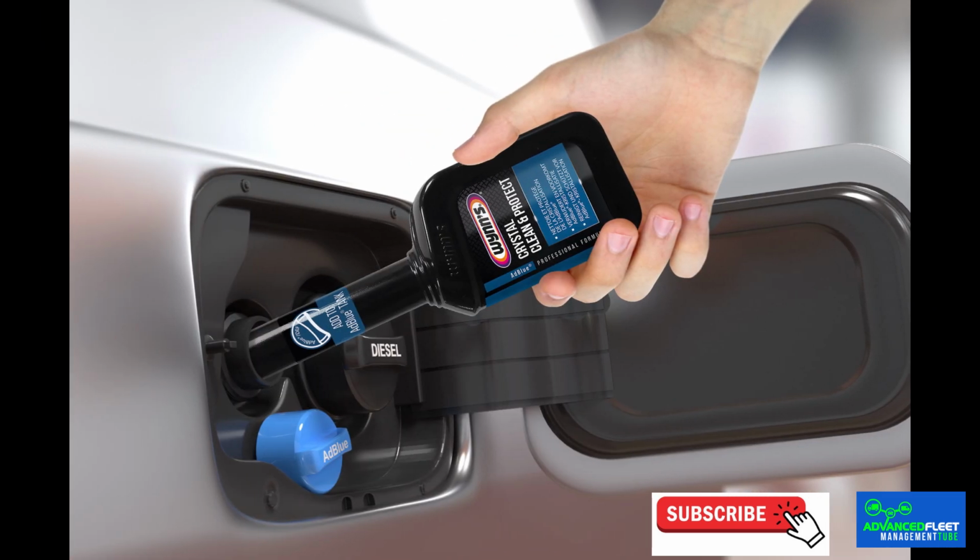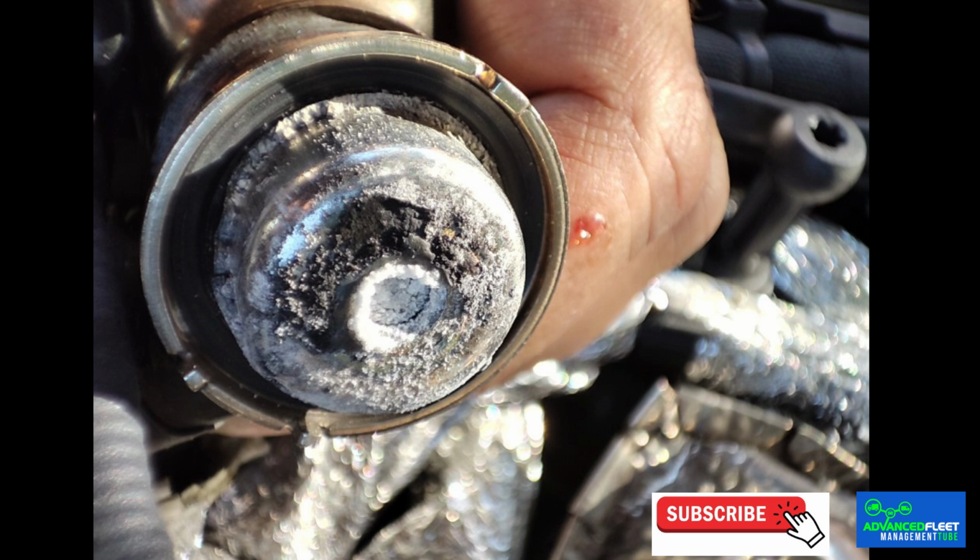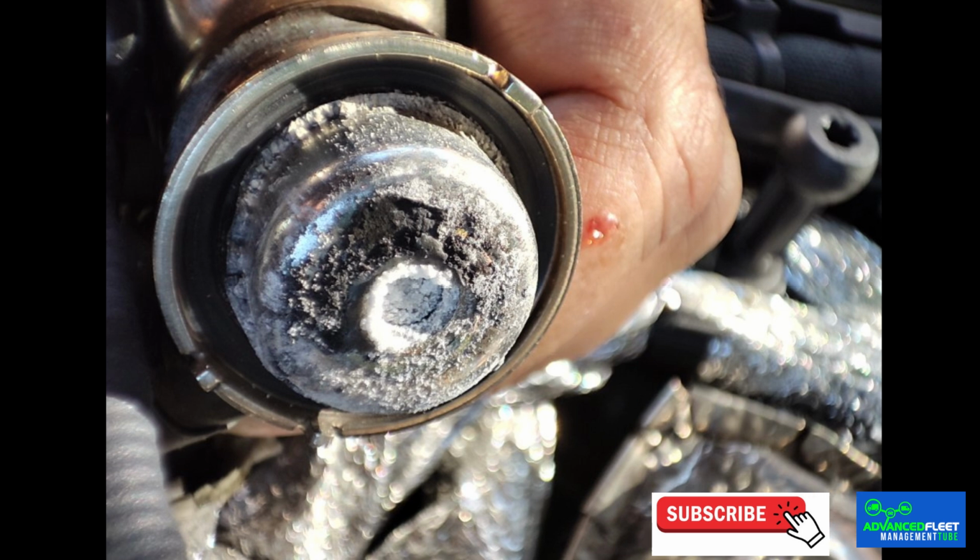Adblue system contamination. Contamination of Adblue can occur if the fluid is mixed with foreign substances that alter its chemical composition. This can compromise the efficiency of the selective catalytic reduction (SCR) system and increase the vehicle's pollutant emissions. Adblue injector problems. Adblue injectors can become clogged with crystals or debris, which prevents correct dosing of the fluid in the exhaust system, resulting in increased pollutant emission.